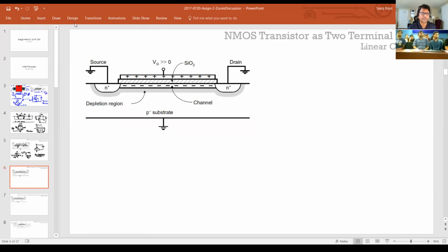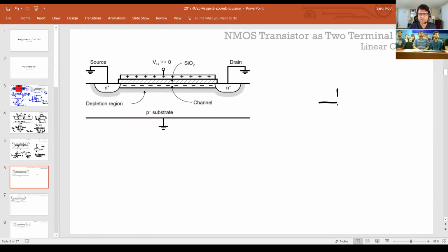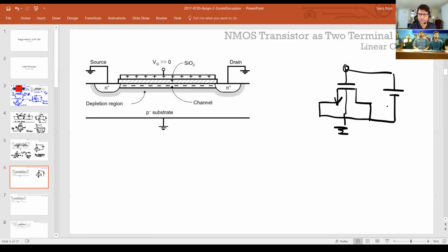All right, so you have the same NMOS transistor now. We take the bulk, source, and drain, all of them connected to ground, and take the gate, but now we start putting a positive voltage, okay? So we slowly vary this positive voltage. This is VGS, which is with respect to the substrate or the source, they're all the same.